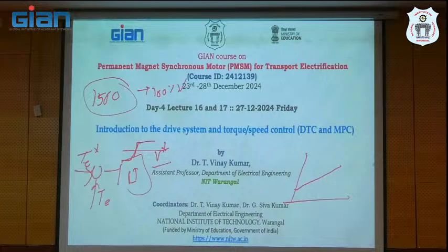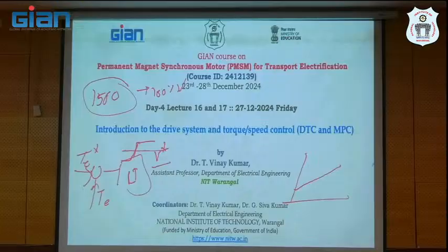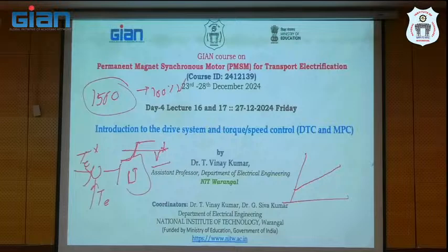Whenever you want to control the current in open loop, you have to see what the main cause component is. The main cause component that accelerates the current is the potential difference between the voltage and the back EMF. These two, the difference between back EMF and voltage, you need to take care of. When speed is 0, the applied voltage must be 10% of the rated value. Like that you have to write the code, you have to write the program.